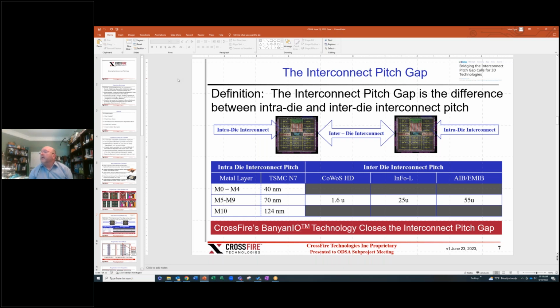Yeah, not that I'm aware of, and in particular, the research I did on CoWoS was fairly brief. I was more interested in the pitch, but the number of layers is obviously relevant, along with the trace and space. I remember the CoWoS trace and space being pretty dense, but a lot of that is deceptive because vias matter. Every time you put down a via, you're blocking routing tracks, and the vias are typically significantly larger than your trace and space pitch. Thanks.